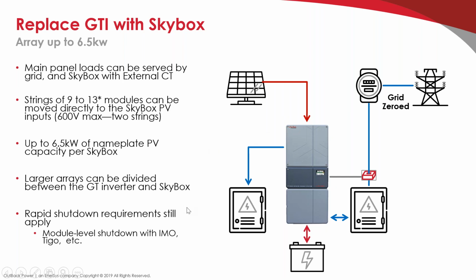Okay, and I already talked a little bit about rapid shutdown. I want to just mention a couple more things about that. There is an application note that we wrote about the different options we have for rapid shutdown. So it's just a switch and a relay, or our RSI switch, and a 24 volt power supply, a little DIN rail power supply. So our rapid shutdown solutions are much simpler than they were when we had the 2014 ICS Plus box solution, and very easy to implement.